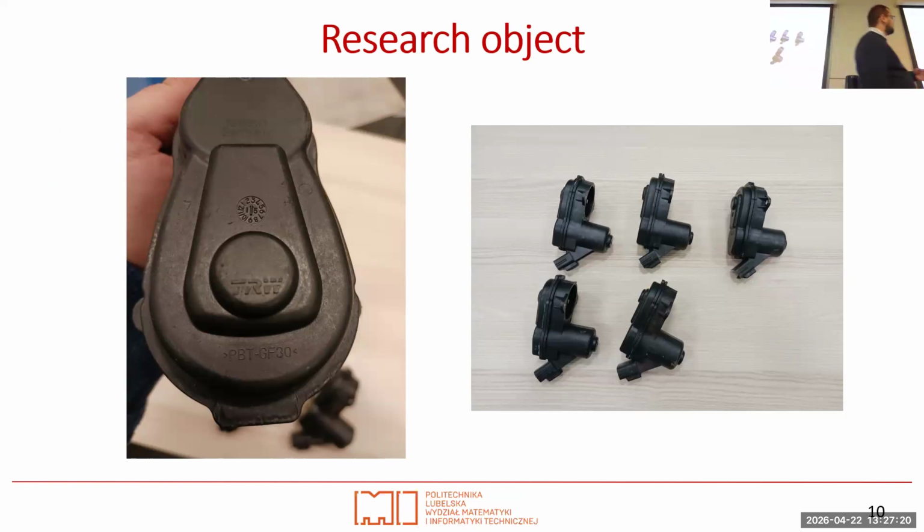This is actually, as you can see in my hand, one of the EPB modules. We have a standard 12 volt connector. However, as you can see over here, it is glued from two parts of the housing, and on this side everything is closed. We have a connector, and an electric motor combined with one of the pinions. The pinion is interconnected with the planetary gearbox for a high pressure force, and it acts on the brake calipers. This is what is outside of this system.